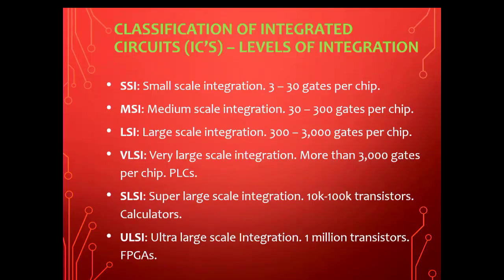So those of you who have already bought the Basys 3 board, right in the middle of the board you'll see a chip that has XC7A35T-CPG236. That's the heart or the brain of your Basys 3 board. It's got millions, I think it's got over 5 million transistors and 32,000 logic cells inside. And this is just a normal, below standard FPGA. Those which are very expensive, like I'm talking about $5,000, have like a billion transistors in them.